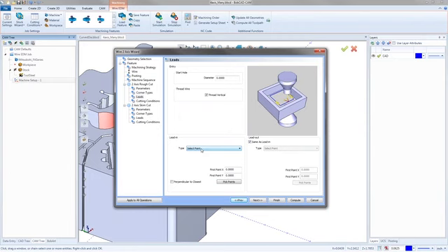And then in version 31, I don't think it was in version 30, I could be wrong, don't quote me on it fully, there's perpendicular to closest. After you pick the point, if you check this button, it's going to make a perpendicular move from that point to the closest wall, and that's where it's going to start the toolpath from. That's how it determines where to set that cut up. You can also move the start point around, but if you have this button checked, it's going to automatically go to the closest.